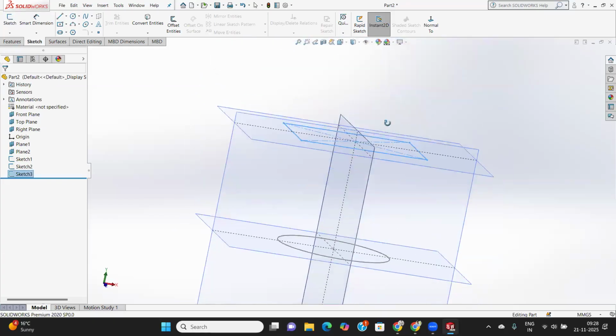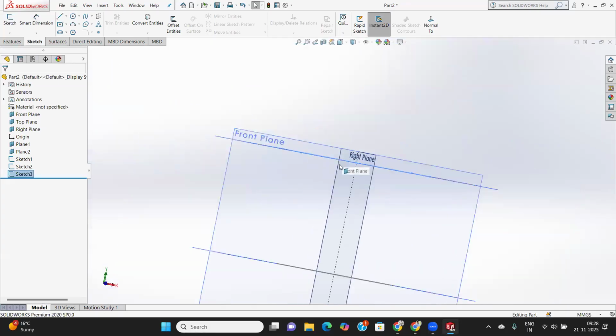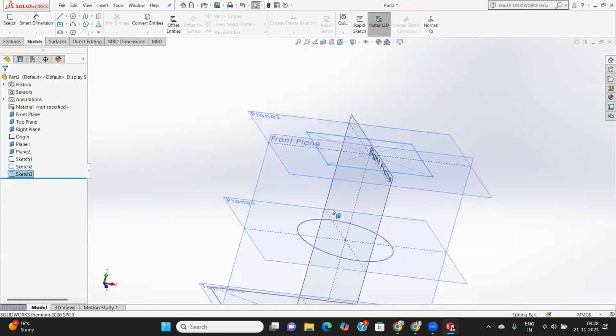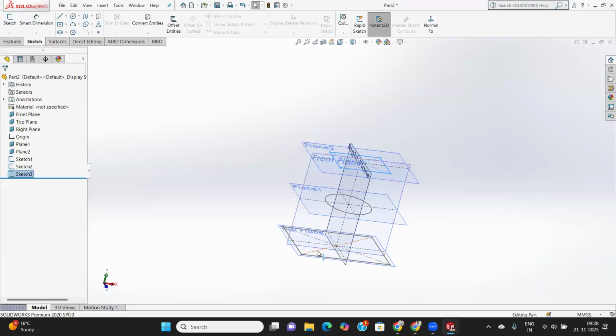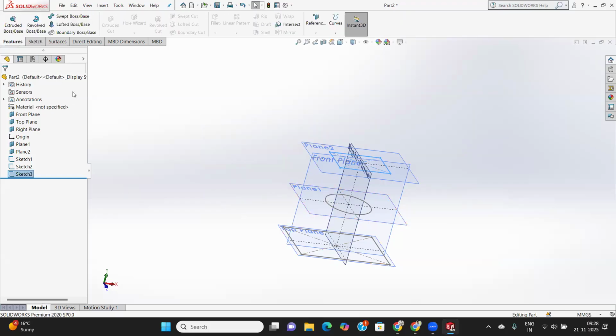First of all, we have to see here your rectangle, then circle, then the third one. Both the sketches are made in different planes. And this is important because after that you can create a loft. Without the loft, it is just merging your multiple objects right here.